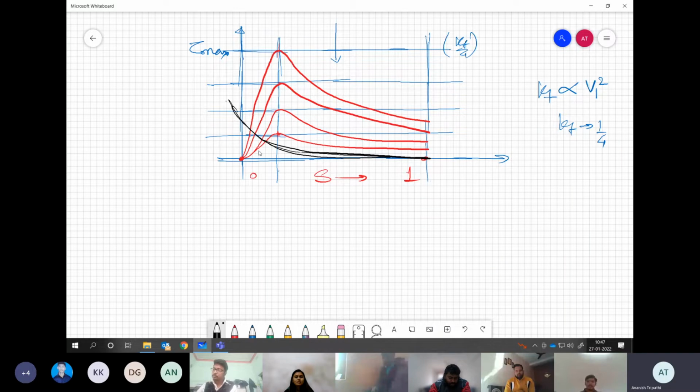So if you have a load to start which is of this nature, like a fan load or blower or any other thing, then this voltage reduction method may be useful, because any starting torque is okay. It can improve, and slowly as you increase this voltage, the operating point will shift and it will come to its natural slip. Correct? So this kind of load is fine when you have this method.